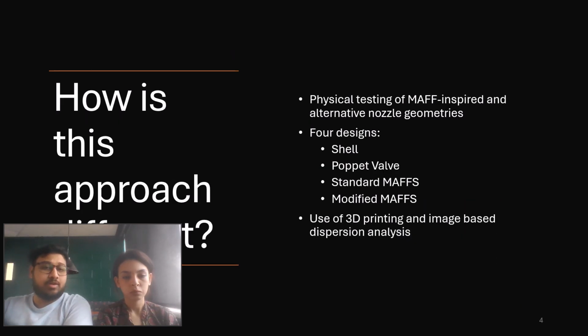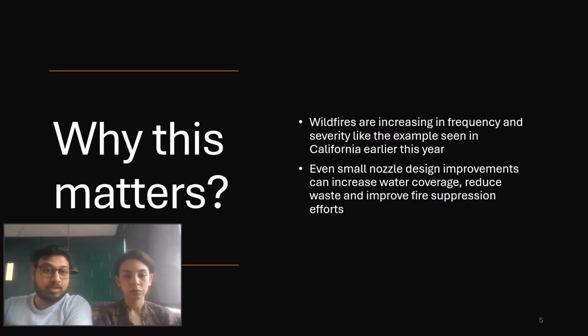How is our approach different? Well, the biggest thing we're trying to do is physical testing of MAFS-inspired and alternative nozzle geometries. We have four primary designs that we are testing: a shell, a poppet valve style system, a standard MAFS system, and our modification to the MAFS system. Use of a 3D printer and image-based dispersion analysis will help us quantify and qualitatively understand how the flow rate and dispersion change based on nozzle geometries. Nobody has ever conducted small-scale physical tests of MAFS nozzles, so we thought it would be interesting.